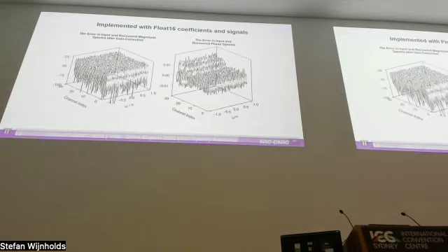This diagram shows the difference between the input and output magnitude and phase spectra, post passband ripple and propagation delay correction, where both the data and coefficients are represented with Float16 format. Here, the stopband attenuation is reduced to about 29 dB, and the level of phase error differs between the channels. For applications in radio astronomy, such variation may lead to bias and therefore needs to be handled accordingly. Similar behavior has been observed for the representations with Posit16, linear takum 16, and TensorFloat32, respectively.